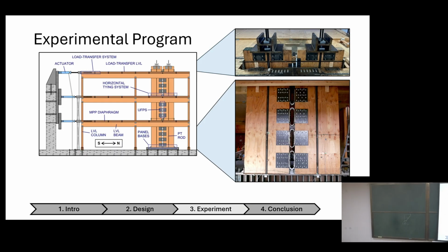So this is the saddle at the top. There are two post-tensioning cables for each panel, and to each of these cables we hooked up a jack and post-tensioned to 93% of yield. On either side you see this plate, and there is a steel bar going in and out of this plate here, and that's what's transferring the lateral forces at each floor level.